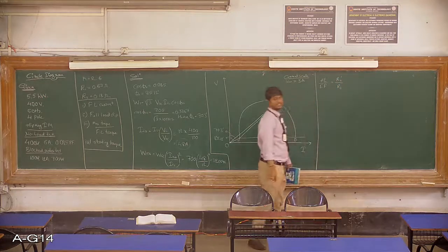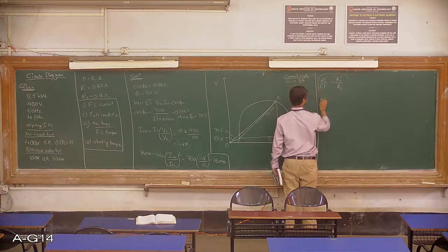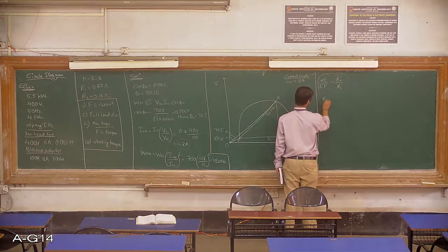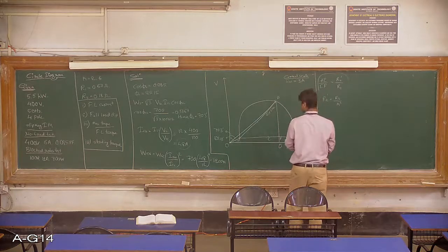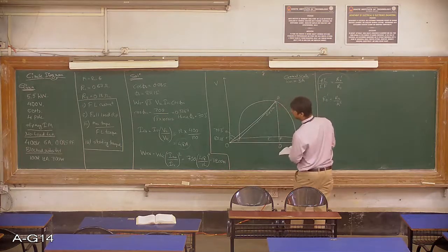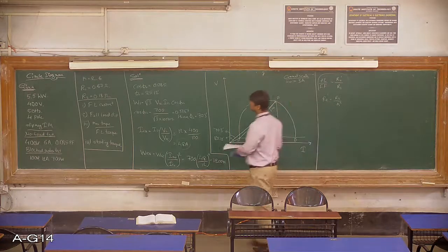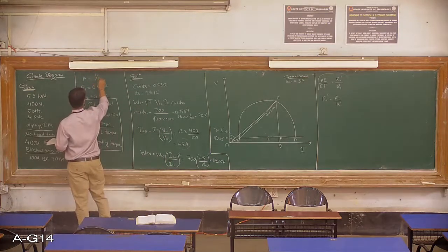We have already derived that for the slip ring induction motor, the ratio of AE to EF is equal to R2 dash to R1, and we also know that R2 dash is equal to R2 by K square. Now the value of R2 is 0.18, and this ratio K is 1 upon 2.6.